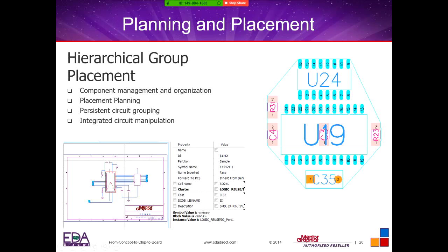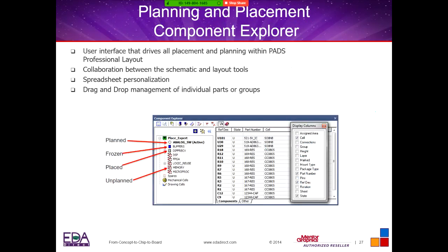You can actually just add this property called cluster, give it a name, and then put a window around all the components in the schematic. Once you push this into PADS Pro, now everything will be inside of a little circle, all the components that are placed on that schematic. Makes the placement a lot easier.